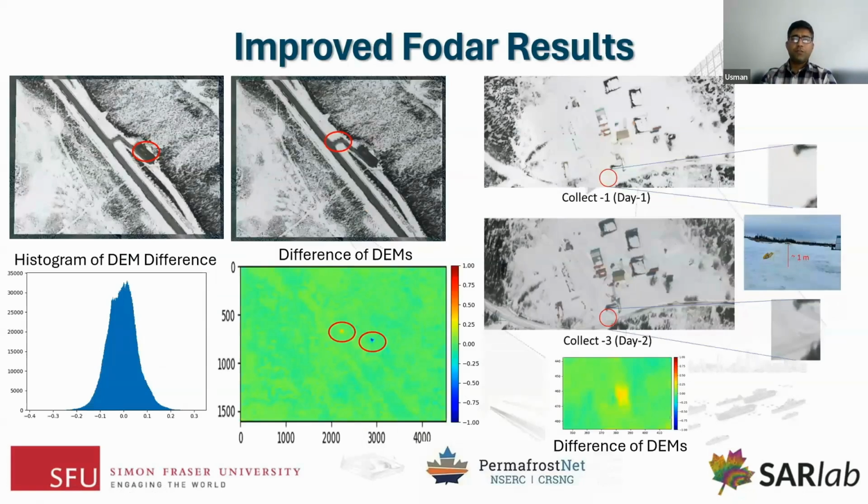Once we looked at the difference of the DEMs for this area, after processing it with the local differential station, we could see that these 2 points appeared as we expected. So our suspicion was probably right that the differential GPS accuracy is causing the repeatability issues. We could achieve what we wanted with this one: once we difference the DEMs in this region, the curve from where the car moved to where it moved was clearly visible in the difference of the DEMs.